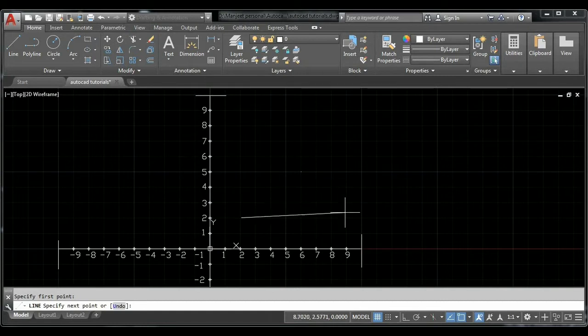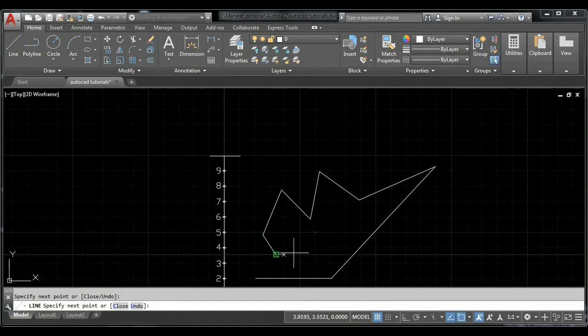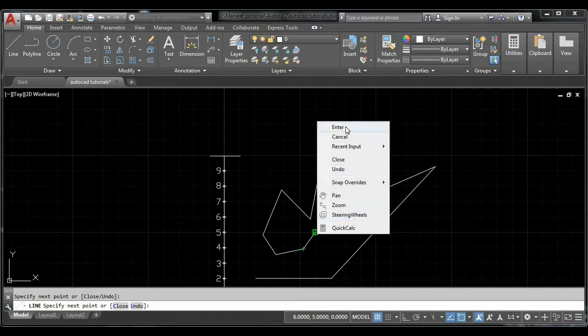So now if I want to make a line in a horizontal direction or at any specified angle, I will directly feed my distance. For example, I feed my distance as 5 units, so it will create a line of 5 units. If I want this line at a random inclination of 10 units, I will show the direction using the cursor and I will just enter 10. So it will create my line of 10 units. In this way, we can create our line at any specified point at any inclination by using the direct entry method.